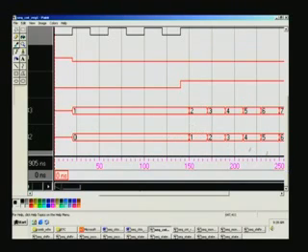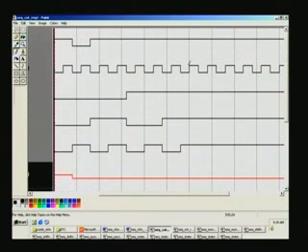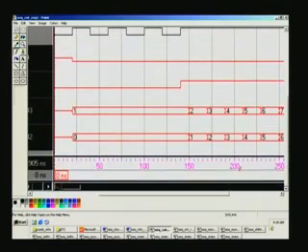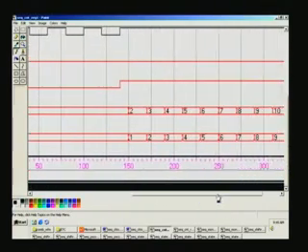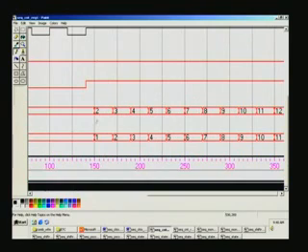You can see that this is the edge that is at 150 nanosecond, and corresponding to that the clock has become active there. That's a rising edge of the clock that is noticed. And here the ABC conditions are 1 here, 1 here, 1. This is ABC, and reset is no longer active. It's active during the low phase here, and you can see the counting progressing smoothly by 1 at every clock pulse.